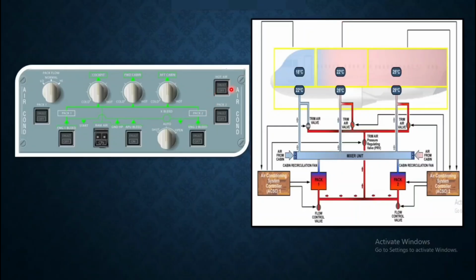And you can see on off means just on off. The valve will regulate the hot air pressure. If it is off, the valve will close and the trim air valve will close, and the fault circuit is reset. The fault light will come on amber color along with the associated ECAM warning when the duct overheat is detected and temperature reaches 80 degrees Celsius.